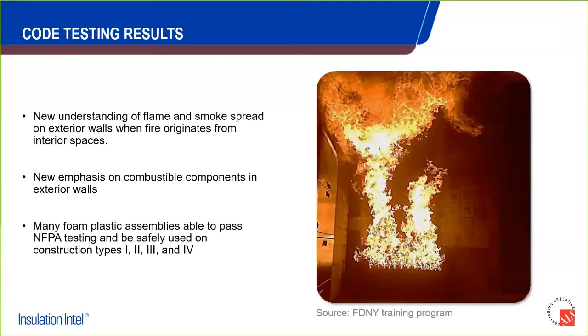Foam plastic assemblies were really the original trigger for NFPA 285, which included non-combustible elements in these exterior walls. I want to underline that this is completely different from a UL type assembly. It's not the same evaluation metrics, and it's also not the same evaluators.